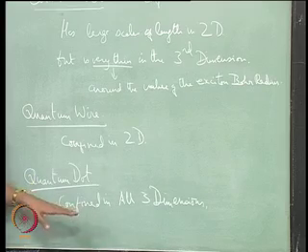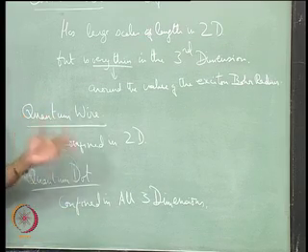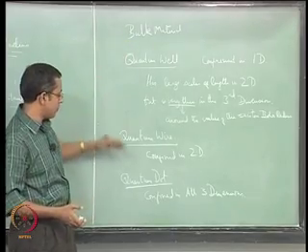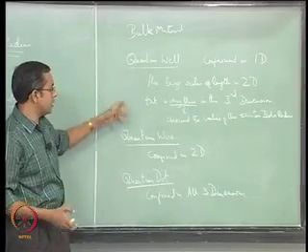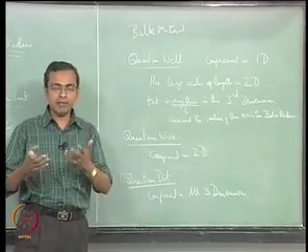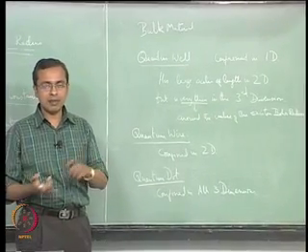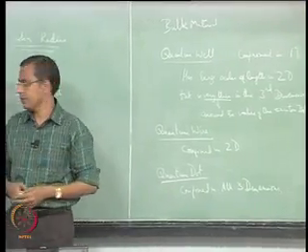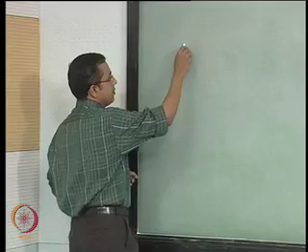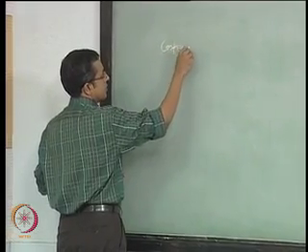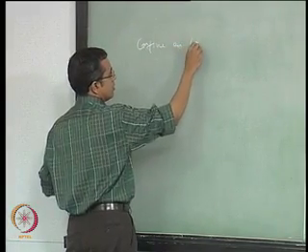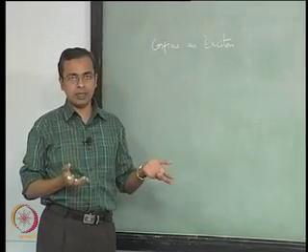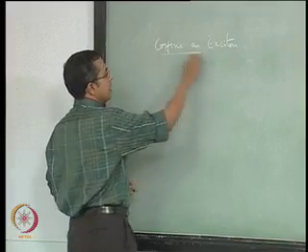So there are a lot of challenges here to get these materials made in the form that you wish to use, so that you can test them, okay. In the process you can create quantum wells, quantum wires and quantum dots. In each of these cases you are confining the exciton in either 1 dimension, 2 dimensions or 3 dimensions. So what is the impact of confining an exciton? When you confine an exciton within dimensions that are of the order of the exciton Bohr radius, then what happens is it impacts the band gap.